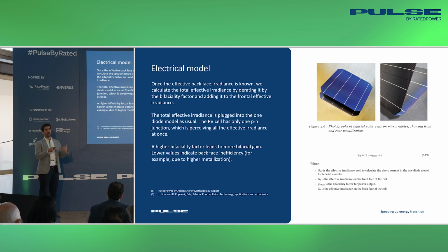So we lose more light due to the aluminum busbars than in the front, and we need to consider that. And there may be other effects as well. This information is actually in the PAN file, the bifaciality factor, and it's usually somewhere between 70 and 90%. It varies depending on the technology. For example, heterojunction modules have a higher bifaciality factor, which is a nice advantage of the technology, right?